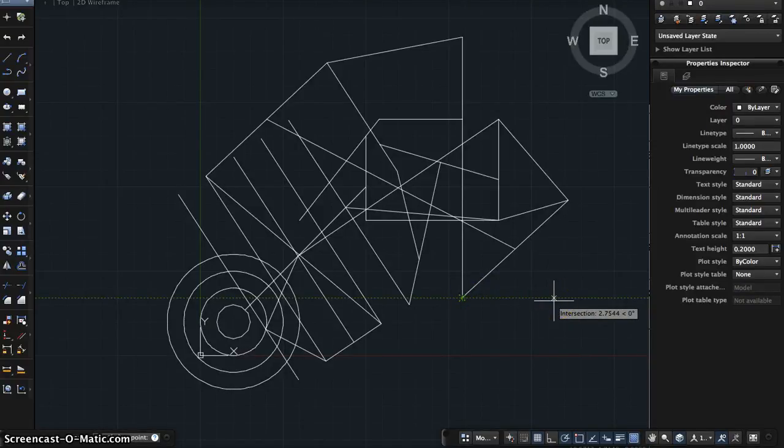See that dotted green line here? Okay. So you can here put your point wherever you want. Let's say I want to add this point to the intersection or on the level of this and on the vertical level of that. So I'd hover above this till I catch it. I'm just hovering. Then hover above that till I catch it. Once I get to this intersection, it will show me the X. That's when I can snap my line to.